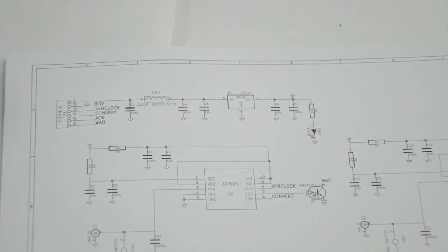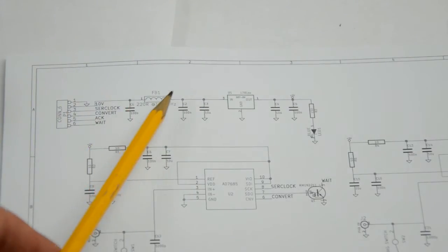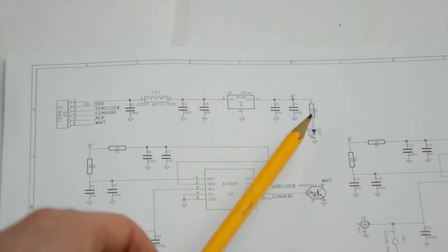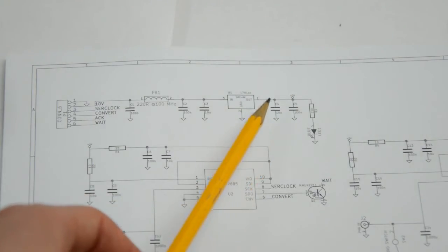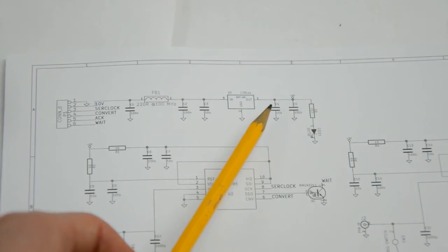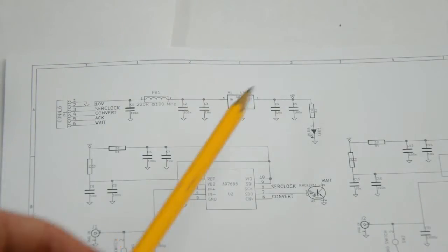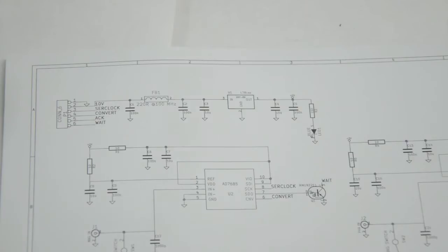The power supply section is particularly boring. You get 10 volts in, capacitor, ferrite bead, 2 more capacitors, 5 volts regulator, 2 capacitors. One of the capacitors is 10 microfarads ceramic, and the other one is 100 nanofarad ceramic, and then of course an LED. So there isn't too much of interest here, although I'll come back to that regulator because it's interesting to look at what you can expect and what you cannot expect from a design like that.